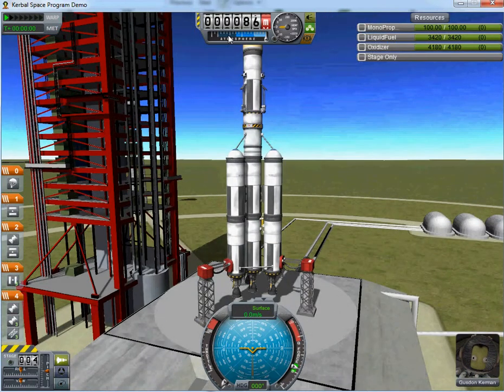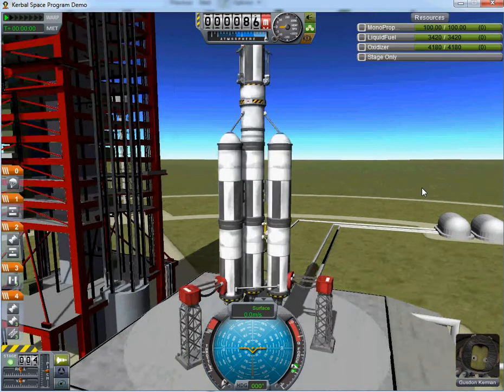Normally what I design everything to do is have enough thrust that I will just about hit my terminal velocity at pretty much every point in my ascent trajectory, and that will mean that, at 100% thrust, I have not put too much engine, and so I'm not carrying too much mass in engine form up with me. I'm basically just taking the very minimum amount of craft and engine and fuel that I need to actually get to where I want to go.